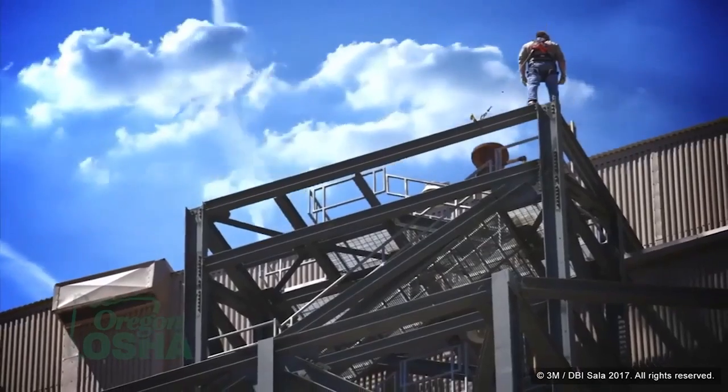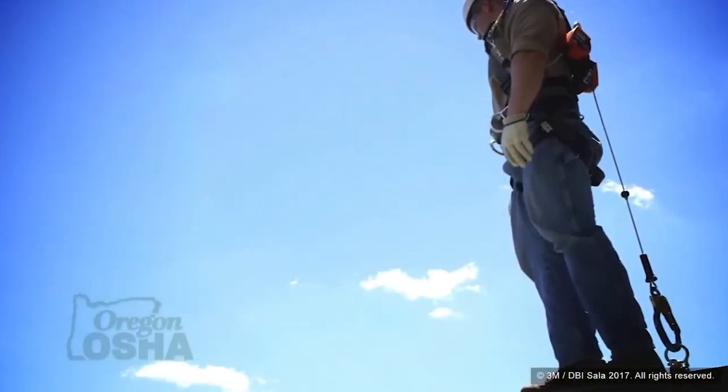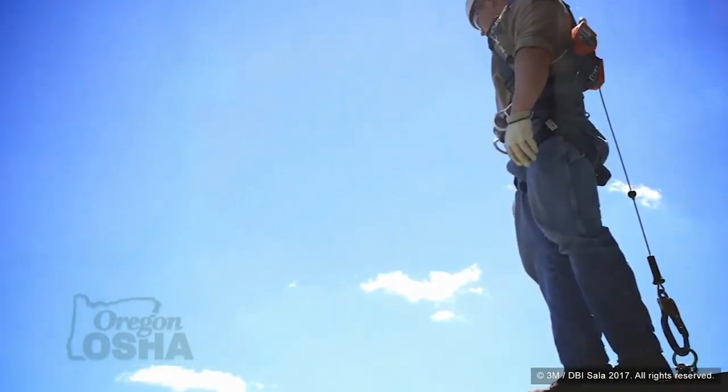If I'm an iron worker and I'm walking red iron tied off at foot level and I take a fall and strike an I-beam with my fall arrest equipment, I have a leading edge hazard, but I also have a sharp edge hazard where I need to make sure that I've identified that as a potential area where I could have a cut hazard. Our qualified people and our competent people need to be on the lookout for these hazards and making sure that workers are protecting themselves and using the right equipment.